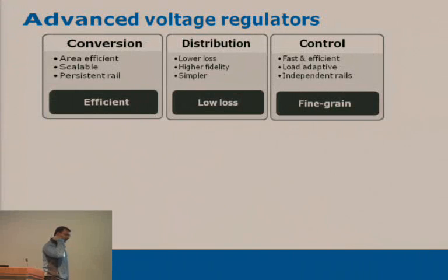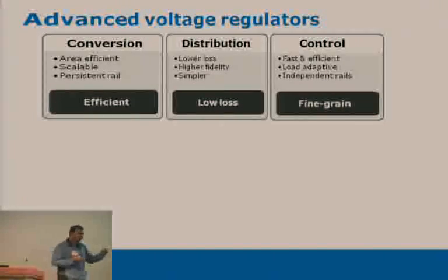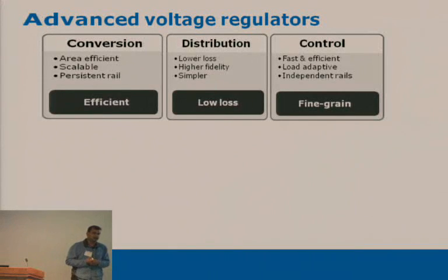One of the key enablers on the efficiency of the packaged microprocessor is the amount of energy you lose in the voltage regulator. And clearly, this is much more severe for data centers, and if you look at the entire data center power delivery distribution. But even for a client, laptop, or even desktop microprocessor, the voltage regulator eats away a big chunk of your energy budget. So one of the ways to address that is really not only make them more efficient, but make them smaller. And the way to make them smaller is make them higher frequency VRs.